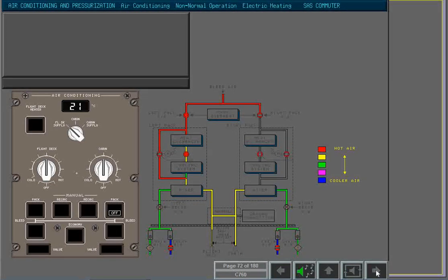Additional flight deck heating is available electrically via the air-to-floor outlets, sidewall outlets, and window demisters. Switch on the flight deck heating. The status of the flight deck heating system is annunciated by the white on indicator in the push button.